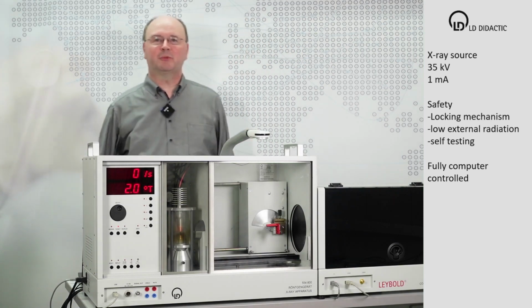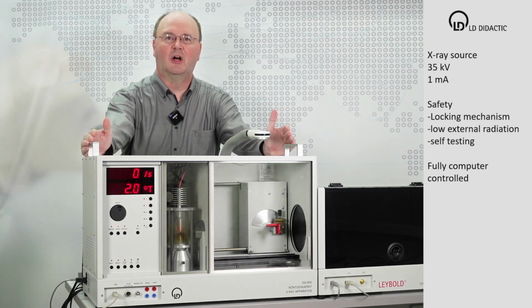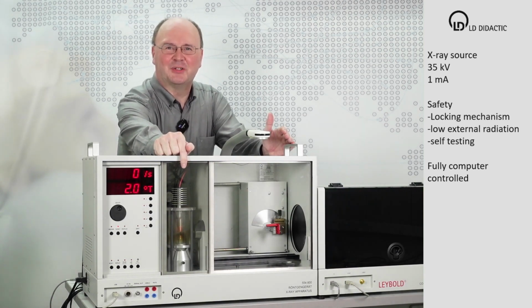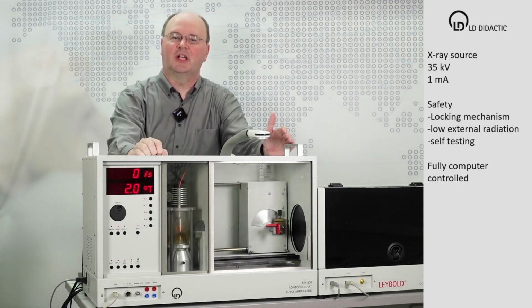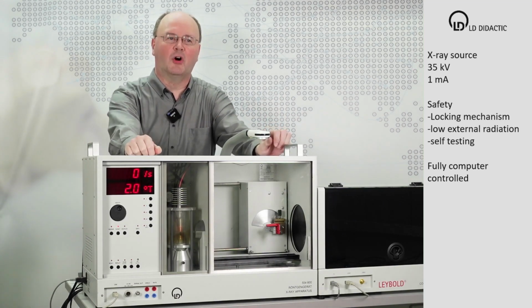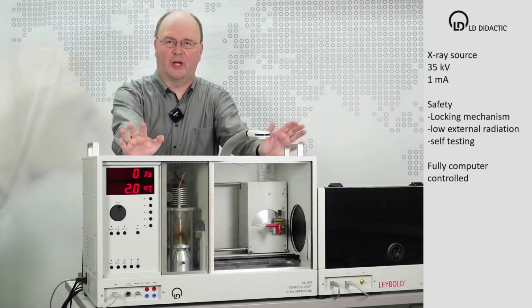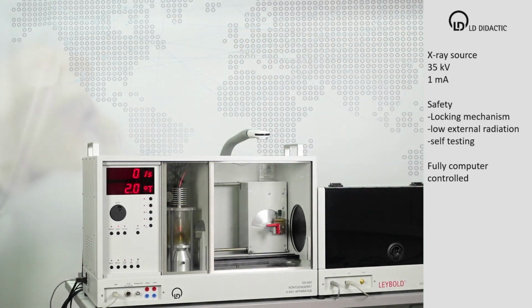Talking about the X-ray machine, this from my left hand to my right hand is the X-ray machine itself. We have an X-ray tube here underneath my finger where the X-rays are produced, 35 kV, 1 milliamp. It's not that much, but it's absolutely sufficient to do all the experiments we'll talk about, and for safety reasons everything is shielded here. There is no radiation leaking to the outside. We're talking about microsieverts per hour where I'm standing here, so it's absolutely safe. There is a locking mechanism, and you hear it when I close the doors.